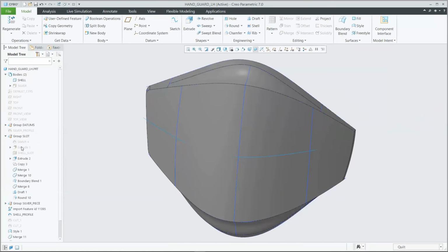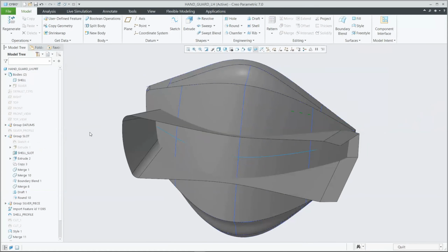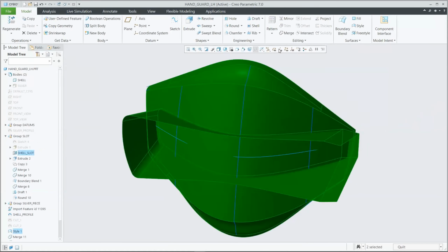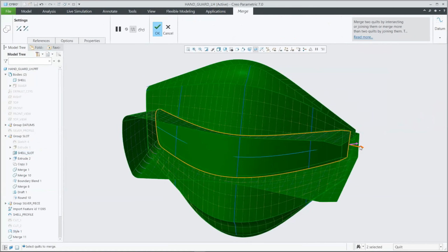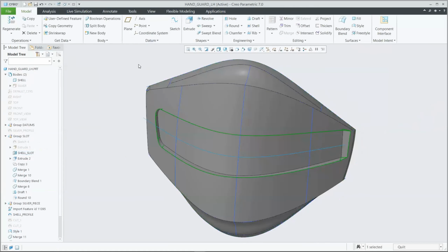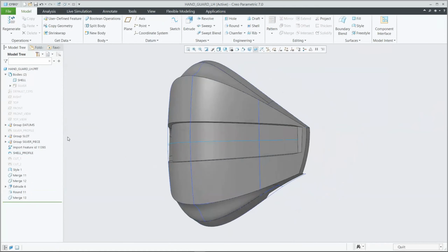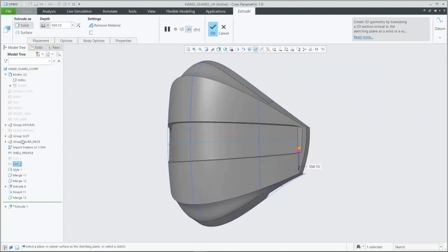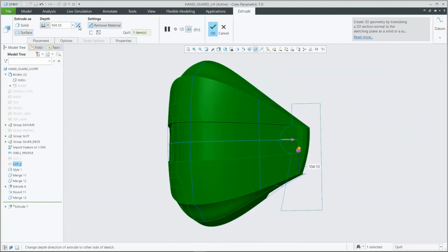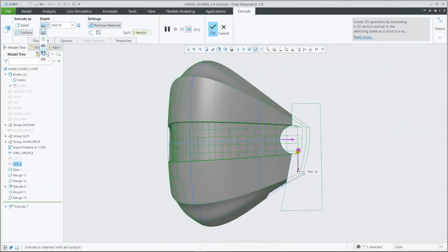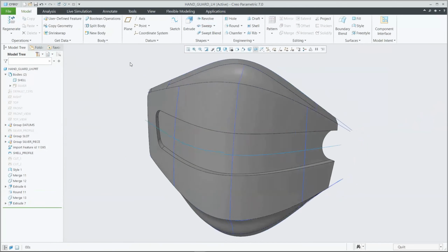Now that we've got this all brought together as one piece, we are going to start shelling out geometry. And this is just based off of that metal piece that we had earlier. So just taking a cutout around the edge there to give it space to come in. And we have the last section here on the right-hand side, which is going to show where that rounded piece on the edge of the metal is. Again, just taking an outline of that. But in this case, I'm going to say I want to remove any material that would fit into there.